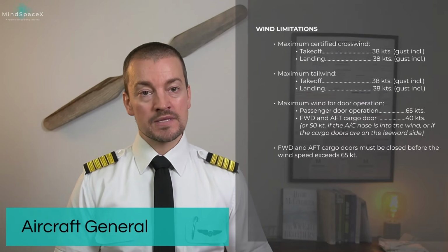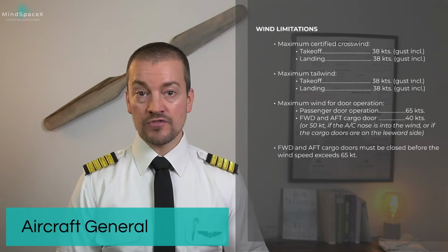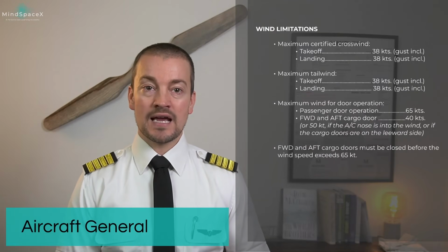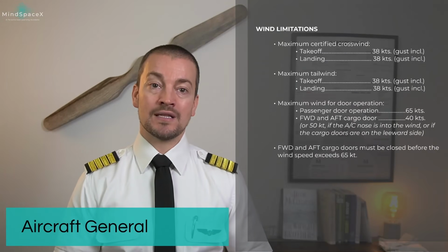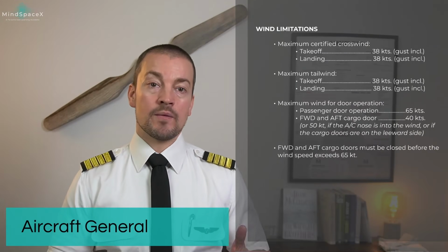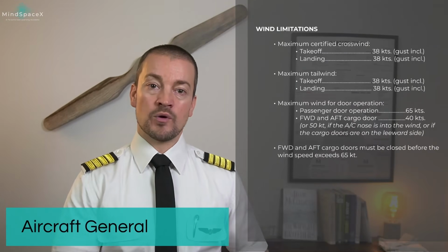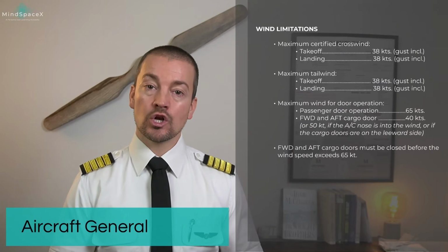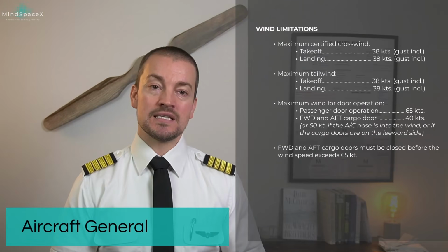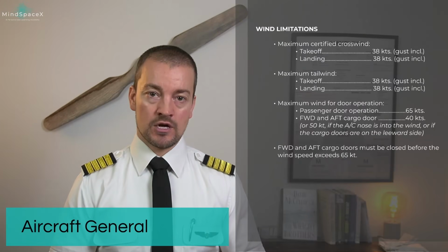However, this limitation can be increased to 50 knots, provided the aircraft nose is into the wind or if the cargo doors are on the leeward side. That means the side away from the wind. Forward and aft cargo doors must be closed before the wind exceeds 65 knots.